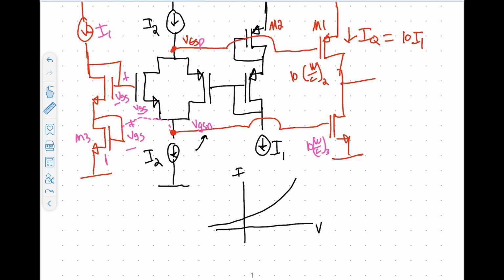So this would be your IP versus the VID, the input differential, and down here you would have, okay, that was pretty bad. Move that. So this should be pretty well centered about that crossing, and this would be your IN. So that's what it looks like. It's able to sink and source in both directions, and you get a significant expansion on the current from what this I min level is down here, and your quiescent bias point effectively.